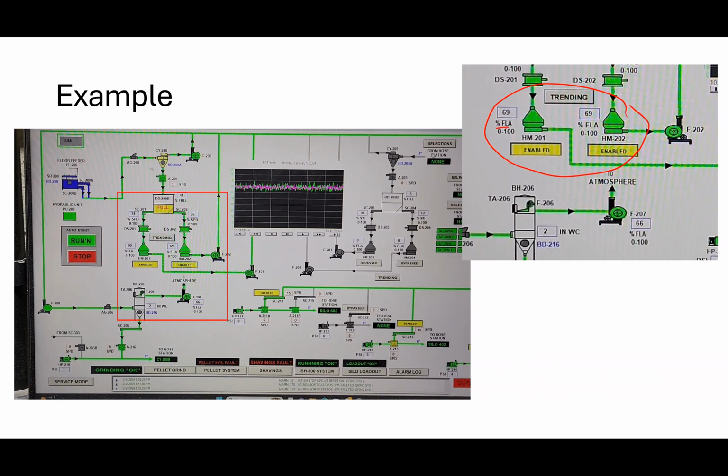This is a pretty common thing to do on a motor. It's basically percent of full load amps, because the motor is rated to operate at a particular amp number. If I get a 200 horsepower motor or a 400 horsepower motor, they're going to have different numbers. And it's inconvenient to be talking about it that way. If a motor is rated for 100 amps, you really don't want it to go above 100 amps. That's not a good thing, because what's going to happen if I'm going over 100 amps if it's rated for 100 amps?